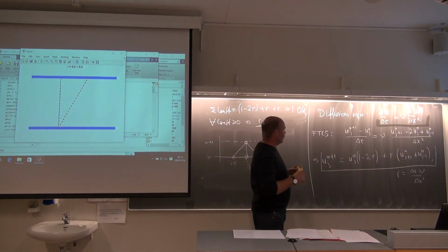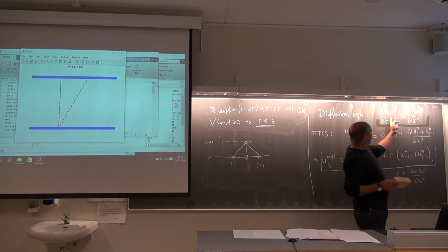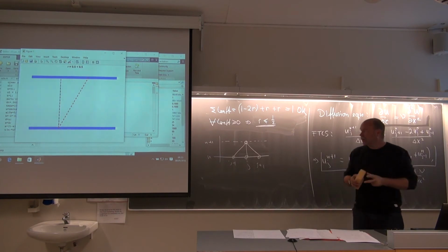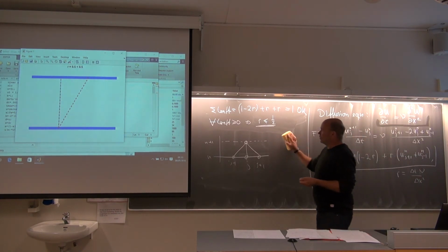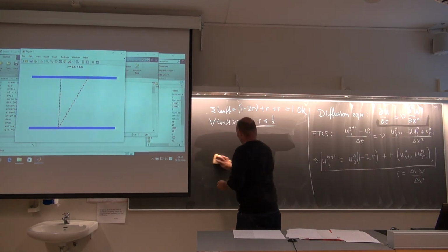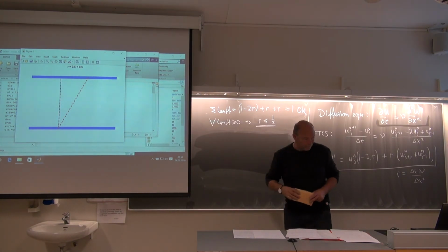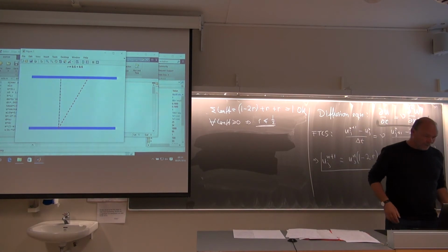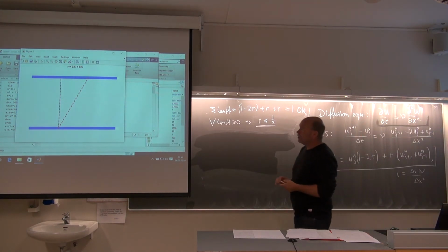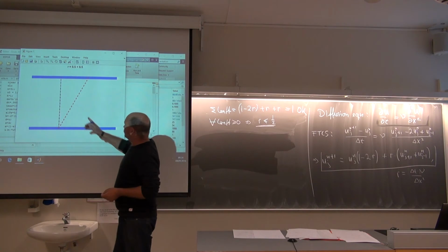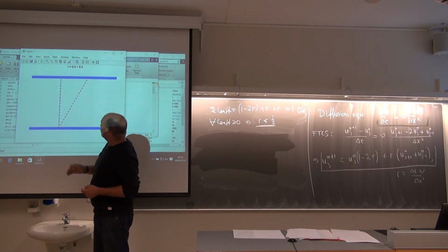These advection terms have disappeared. So this is what you are left with in a Couette problem. What should the solution be? You start with everything equal to 0, and the correct solution should then be a straight line here.